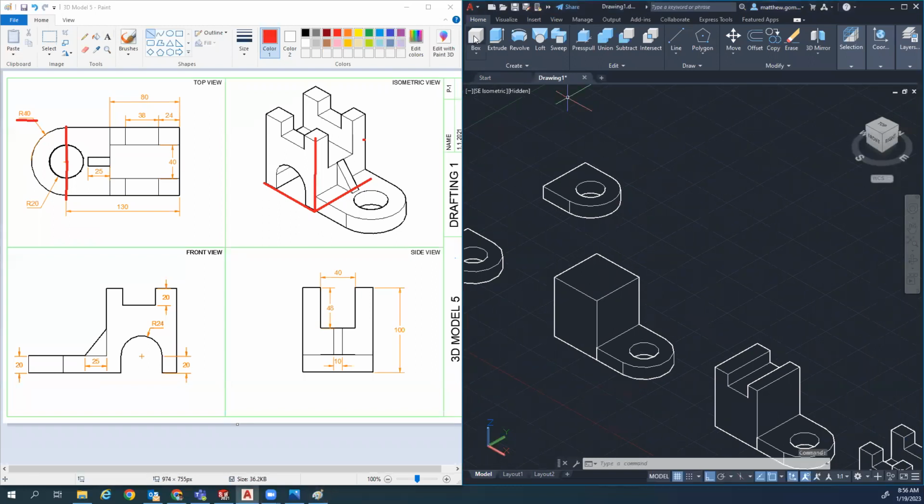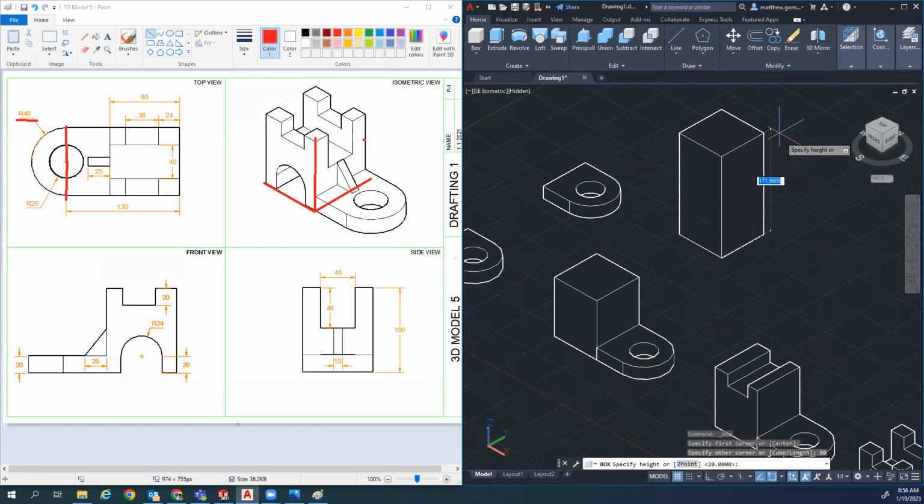Here's a new tool. Box tool creates a 3D solid box. You can just click here, and then you have two values. You can hit tab to go in between the two values, and you can just type 80, tab 80, enter, and then it drags the box up to give it a height. Someone tell me the height of this tower thing. 100 right here.